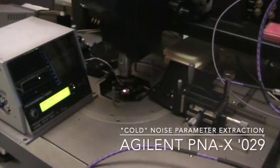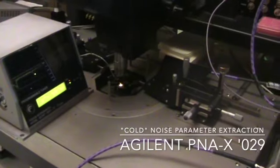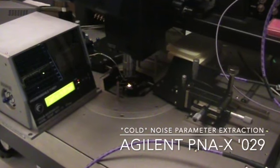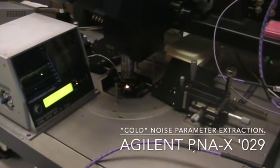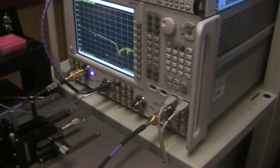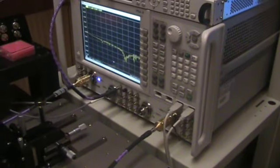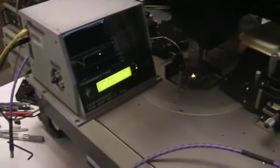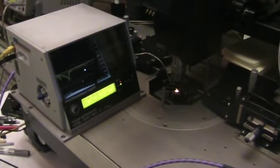This is a series of videos to demonstrate the noise parameter measurement system using the Agilent PNA-X and option 29 native noise receiver. With this particular apparatus, we'll be using a 50 gigahertz Agilent PNA-X, the N5245A. This is a 4-port version with the integrated noise receiver on port 2. Using a wafer prober, manual Cascade 11K wafer prober, and a Focus Microwaves CCMT 2 to 50 gigahertz source pull tuner.